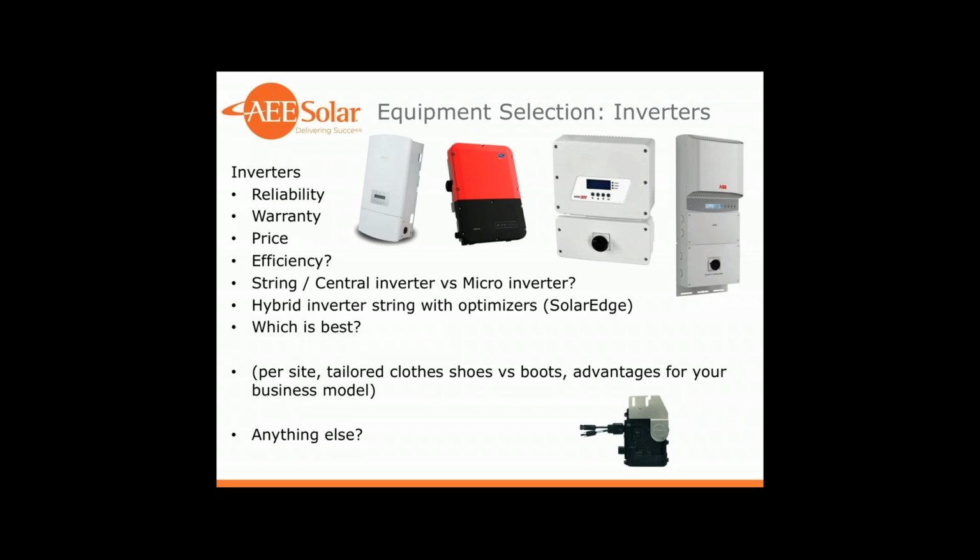So I would recommend a given partner has maybe a higher cost but higher capability inverter system, whether that's Enphase or SolarEdge. That will allow you to increase your power output or harvest on a given job site that has a lot of challenges to overcome. Maybe that's a lot of shade, maybe it's different shaped roof, different elements, hips, valleys, and other things that make it difficult to put in a simple or straight array.